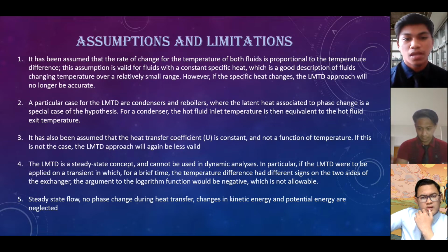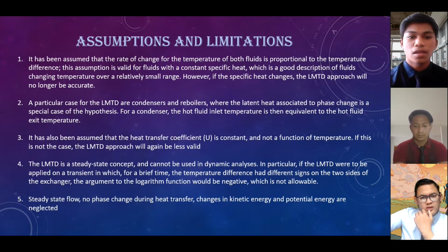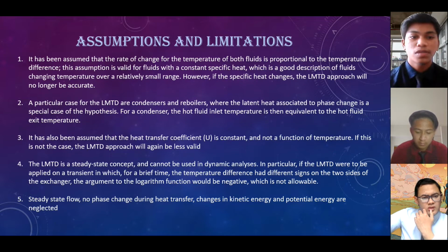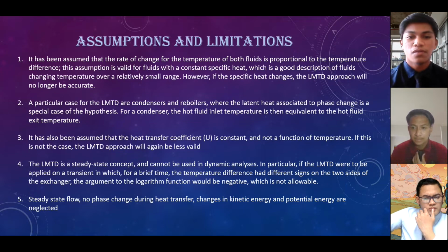For a condenser, the hot fluid inlet temperature is then equivalent to the hot fluid exit temperature. It has also been assumed that the heat transfer coefficient is constant and not a function of temperature. If this is not the case, the LMTD approach will again be less valid. The LMTD is a steady-state concept and cannot be used in dynamic analysis.